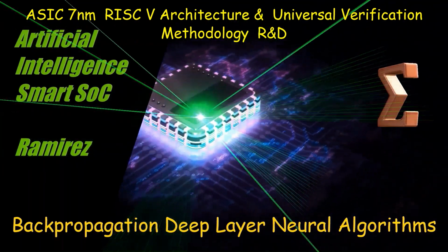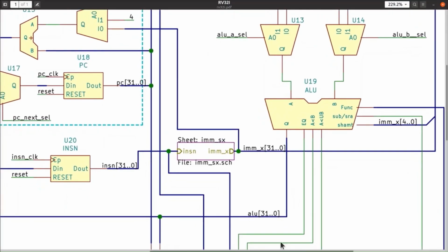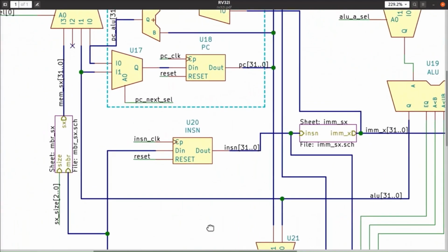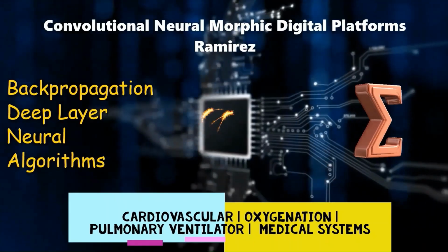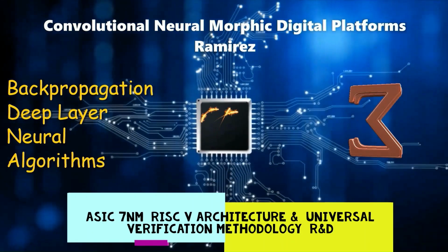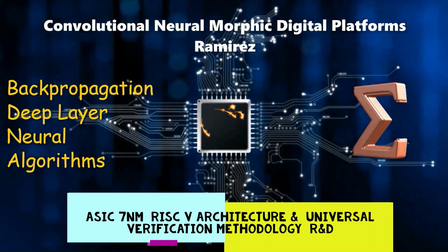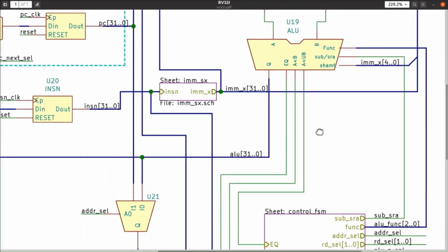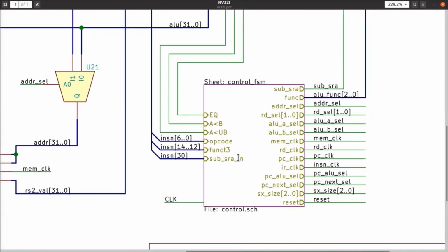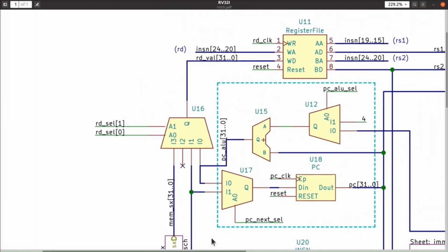Then set clock divider. Test one inverter module with an automatically generated clock on input 0. Set the clock rate to half of the scan refresh rate with make test_clock_div.